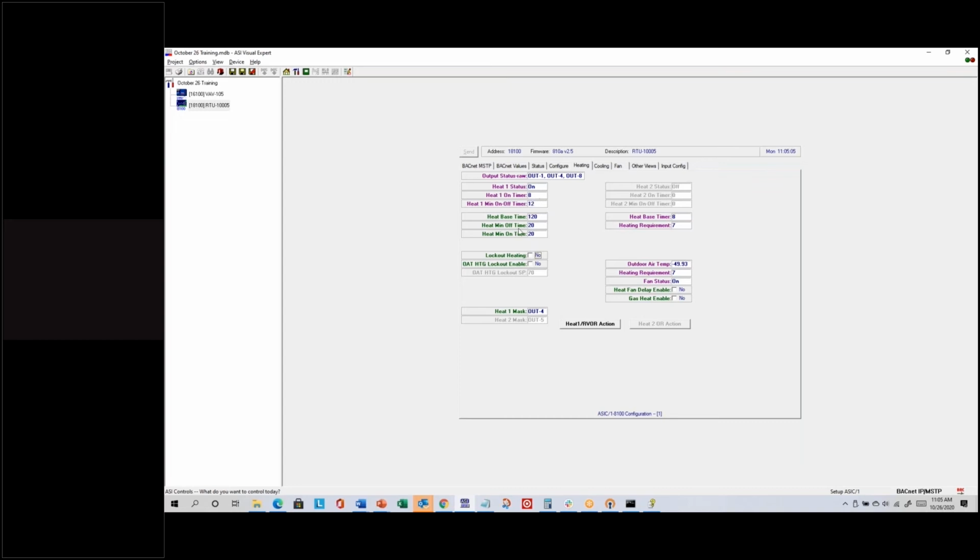So that said, turn on for 8 seconds, but also make sure that once you turn on, you stay on for at least 20 seconds. So it's actually going to turn on for 20 seconds before it turns off. So there's the off, and now once it turns off, it's going to stay off for at least 20 seconds. It's actually going to be longer. Once this heat-based timer resets back to 0 and counts up, then it will turn back on again. The minimum off timer will have been satisfied, so it should turn back on immediately once the heat-based timer counts back up to 120 and starts at 0.